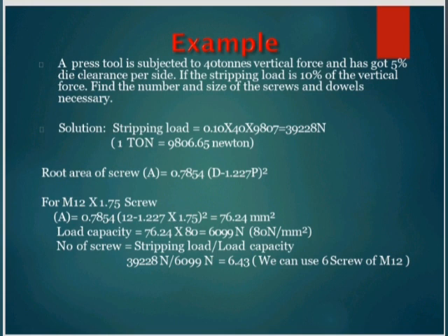Load capacity is equal to 76.24 into 80, which is 6099 Newton. So, number of screws is equal to stripping load divided by load capacity.